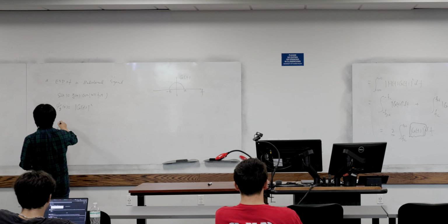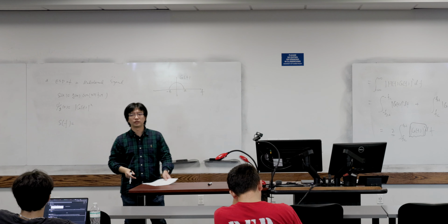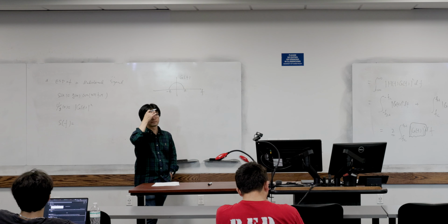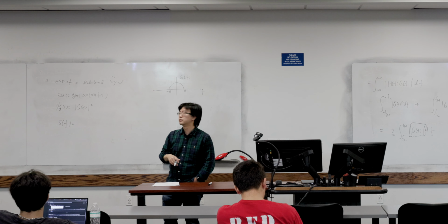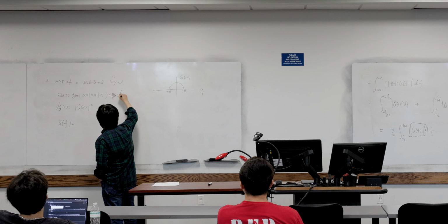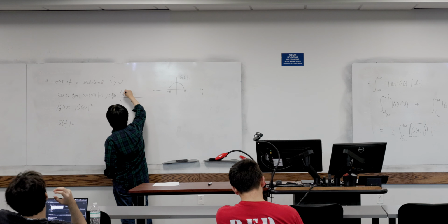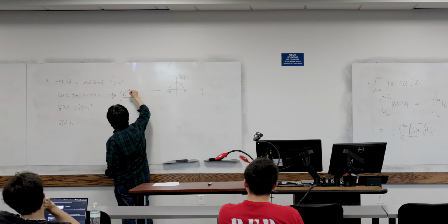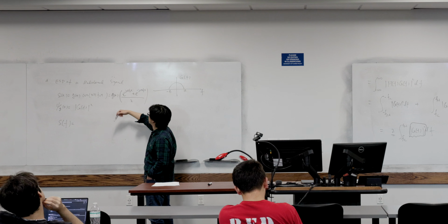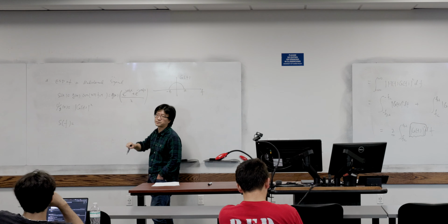So can you tell me what is S of f? What happened in the frequency domain, right? Can you write down S of f in terms of g? We can write that as g of t multiplied by, use complex exponential to represent this, e to the j2πf₀t plus e to the minus j2πf₀t, right? So g is multiplied by one complex exponential and then another complex exponential, right?